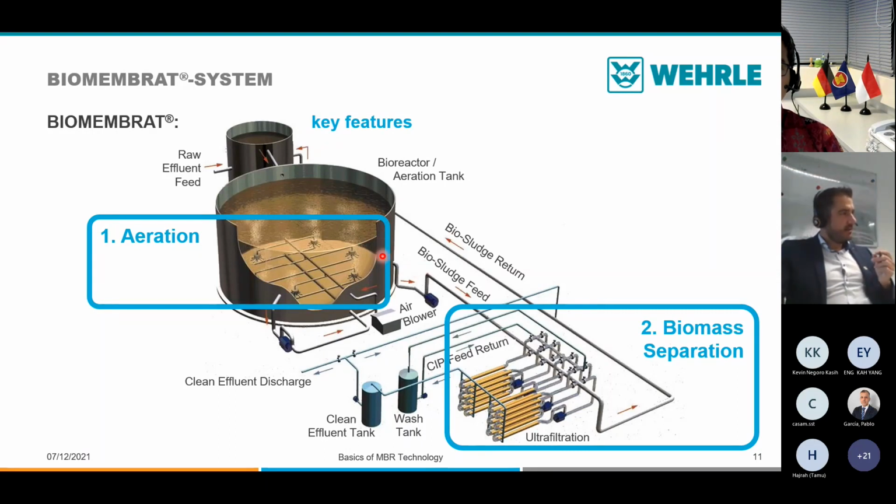The other typical part of our biomembrane system is the aeration system. We do not work, for example, with blade diffusers. With blade diffusers, we made a lot of experience, especially in leachate treatment, that after 1 or 2 years, the surfaces of the blade and the membrane diffusers are completely clogged and scaled, and they are cracking because of the high TDS and chloride values. So therefore, we are using completely maintenance-free jet ejectors. They are also energy saving. They can handle a water level up to 15 meters, which means we can build the membrane bioreactor extremely compact.